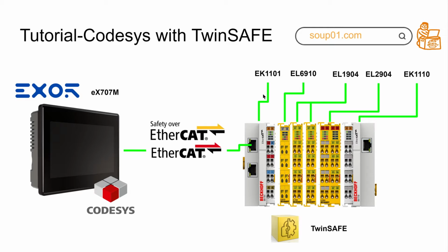For example, the EK1101, the EtherCAT coupler, and the EL6910, the FSoE logic terminal, and then here is the safety terminal. You see here I'm using it. I also show that I'm using the FSoE because I'll show you there's a plugin for Codesys that allows you to control the EL6910 to build the safety logic in your Codesys IDE, and then download the safety project into the EL6910 to build your safety network.